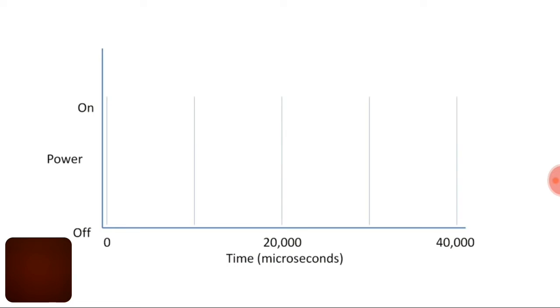If over a short duration of time we turn the LED on for 50% and off for 50%, the LED will appear half as bright, since the total light output over the time duration is only half as much as if it was 100% on. The pulsing width is the important factor here. By varying or modulating the pulsing width, we can effectively control the light output from the LED, hence the term PWM, or pulse width modulation.